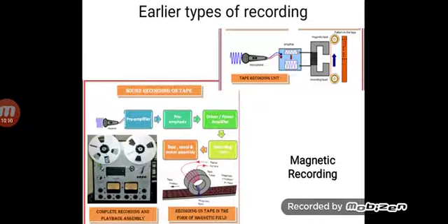According to Faraday's law of electromagnetic induction, this results in current. That current depends on the variations, which is nothing but how we recorded the sound signal. So a similar signal to what we recorded, we get at the time of reproduction, and that is how magnetic recording works.